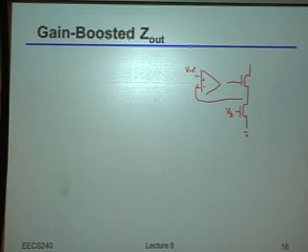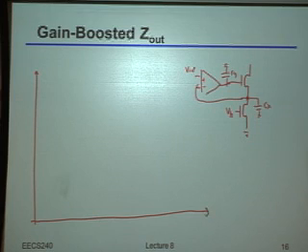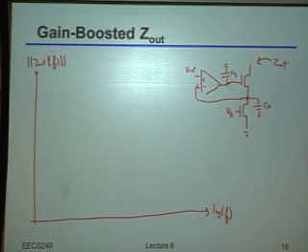So again, let's assume we have something that looks like this. There's some VREF over here. There's some feedback. There'll be, again, some capacitance at that gate there. And we'll put some capacitance at that source node as well. Okay? So now I'm going to draw this rather large. I recommend you do the same because there's going to be a bunch of things going on here in a second. So if I do a plot in the log domain of basically the magnitude of the output impedance versus frequency, okay, and where, again, to be clear, I'm basically looking at Z out over here.